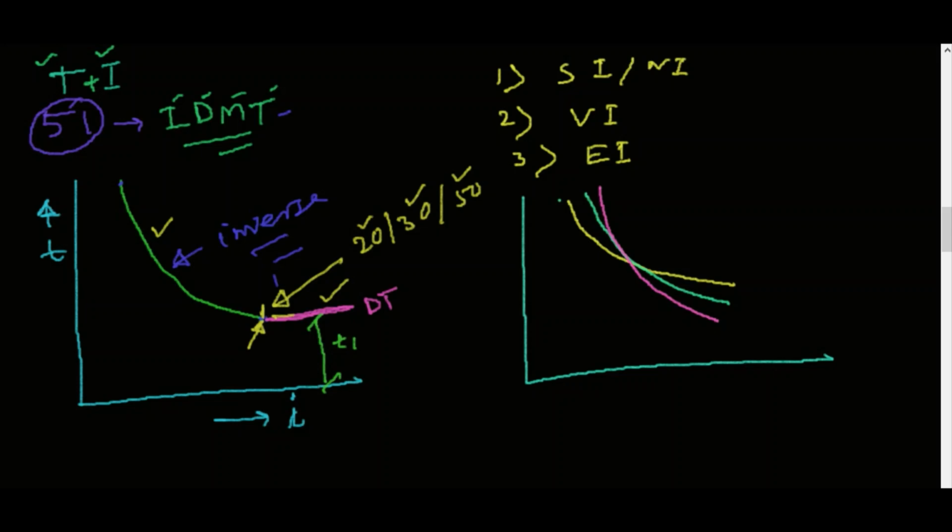So based on the equations for standard inverse, very inverse and extremely inverse, the curves will follow this. With the help of these characteristics, we need to coordinate with the different protective devices.